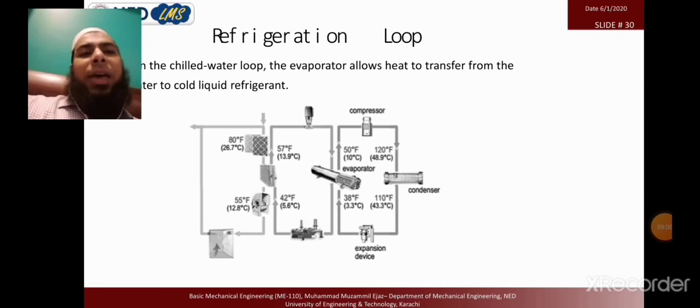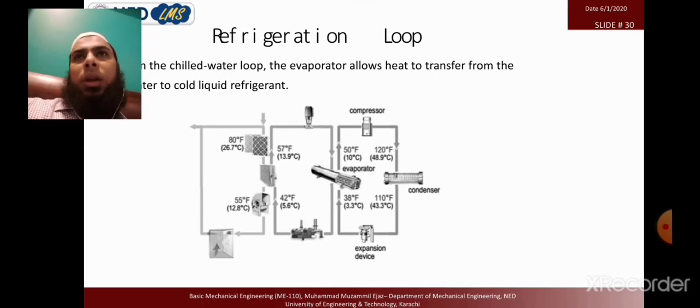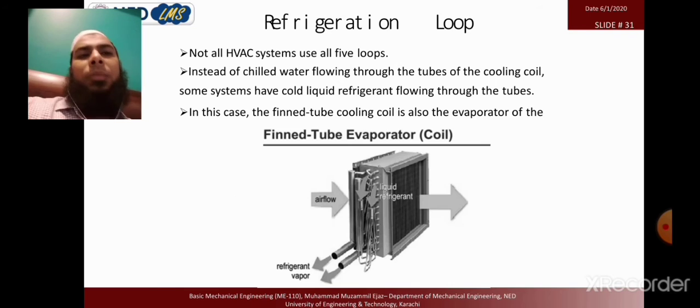Yes, if we have a simple air cooled chiller, the heat is rejected directly from refrigerant to air through the heat exchanger. As you saw in the outdoor unit, in the tube we have a refrigerant and the air is passing through the fins and rejects heat from the refrigerant gas, and the gas changes its phase from gas to liquid, like in this way.